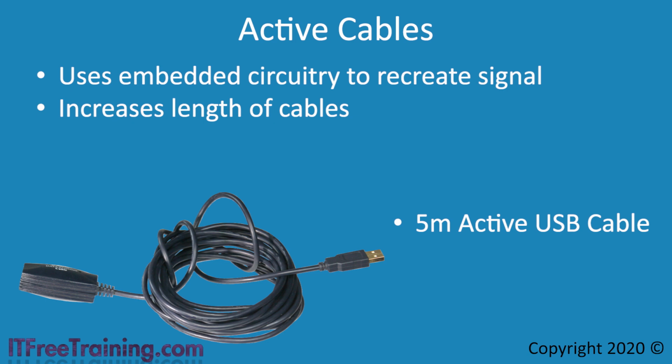In some cases, you may not be able to get a cable long enough to meet your needs. However, you may be able to combine multiple active cables together to get a longer length. Each cable will recreate the signal, but you won't be able to use passive cables as they do not recreate the signal. Generally, the manufacturer of the active cable will include with their specification of the cable how many cables can be connected together. The disadvantage of active cables is that they cost more.